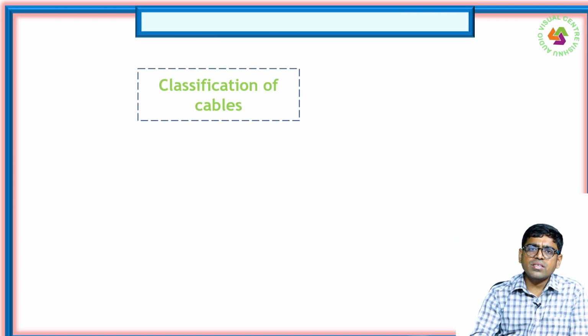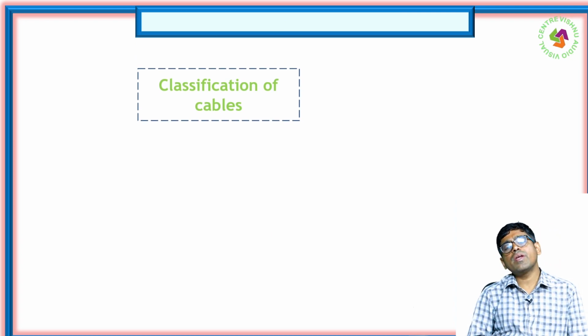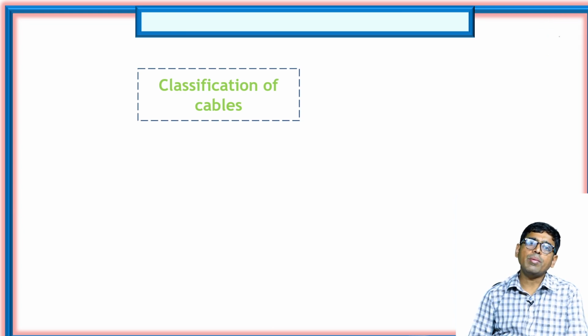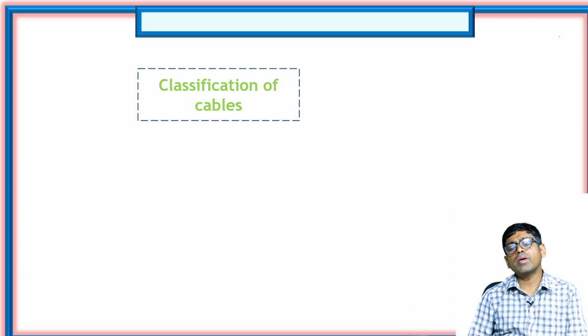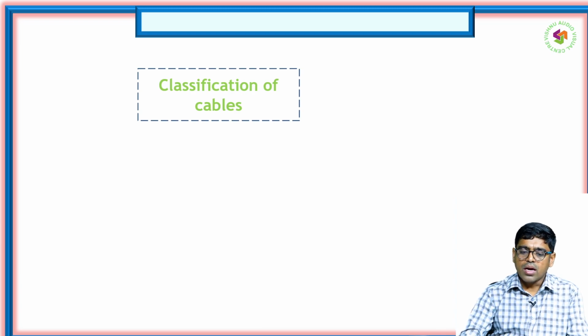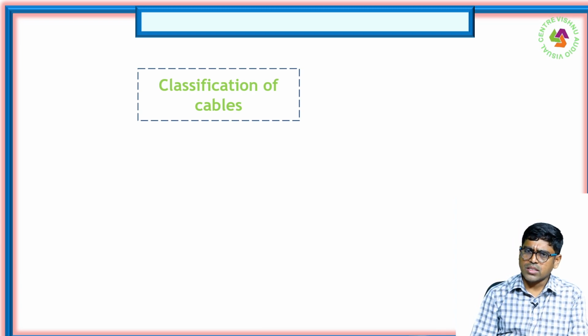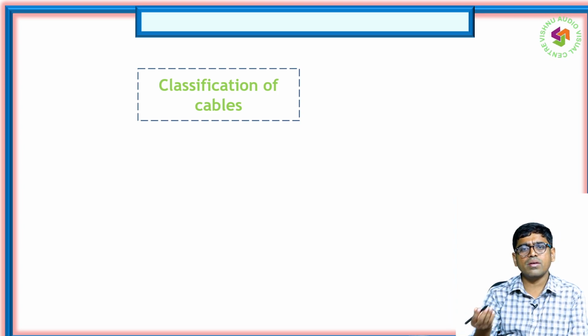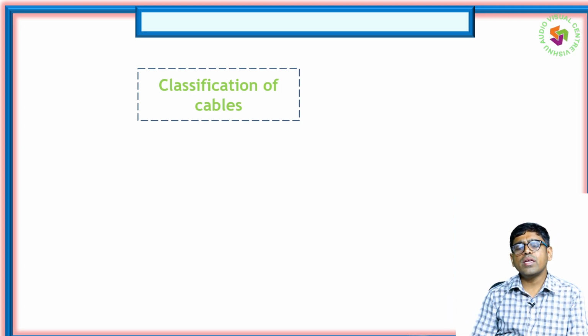And in the classification of this cable, practically we can see the cable may be PVC or XLPE cables. This PVC cable we can recommend for less than 33 kV, and for more than 66 kV we can use XLPE cables. And next, we can see in the transformers, the transmission line, these substations, and the underground cables, they need to connect in the substations.